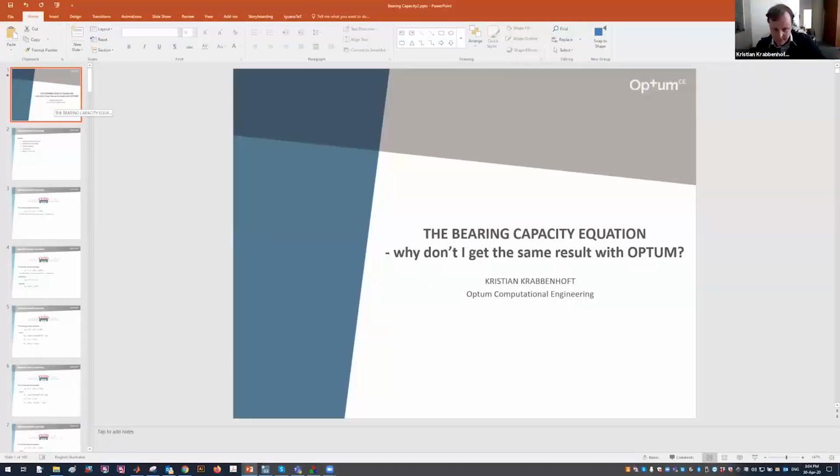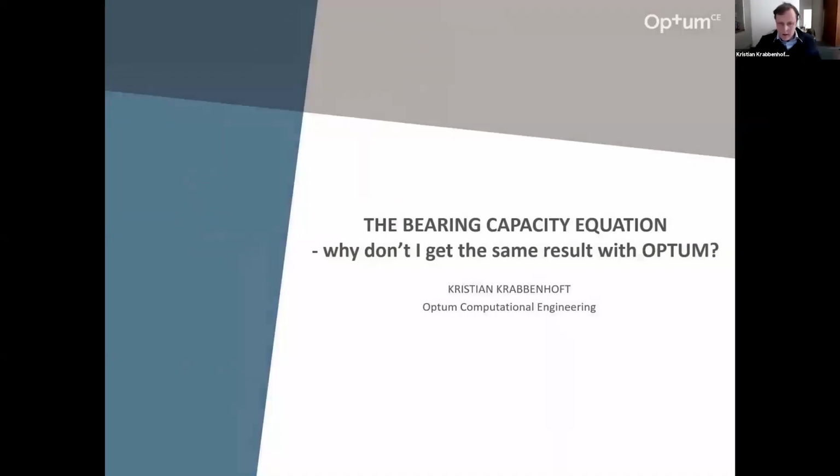The motivation for this webinar was a very frequent question, probably the most frequently asked question we get: why don't I get the same result with Optum as with the bearing capacity equation? When people start using the software, they typically try to reproduce some of the classic solutions, your 2 plus pi, and then move up from there.